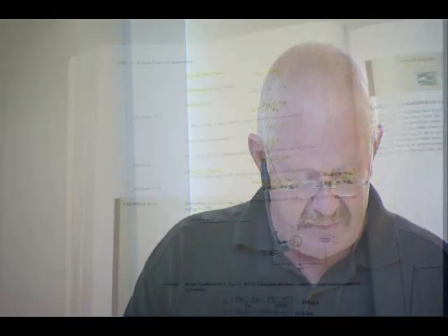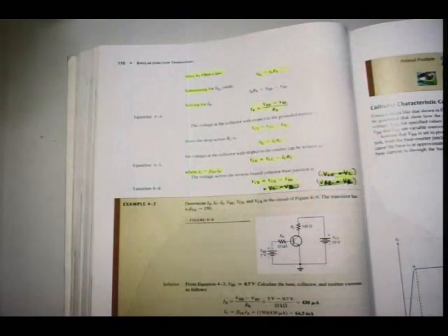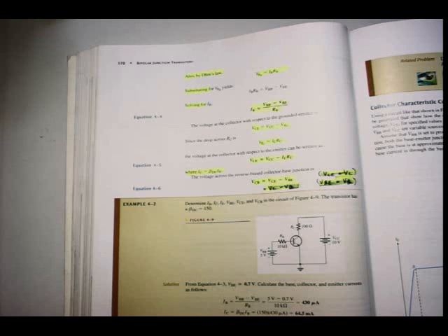And then lastly, the voltage across the reverse biased collector base junction, VCB, as we've seen, is VCE minus VBE. But we've also seen that VCE is equal to VC because of no resistor at the emitter, and VBE is also equal to VB because there's no resistor at the emitter, so it will be the same. And then, as I just mentioned, scratch it in there right next to it, so if you also want to do that, you're welcome.